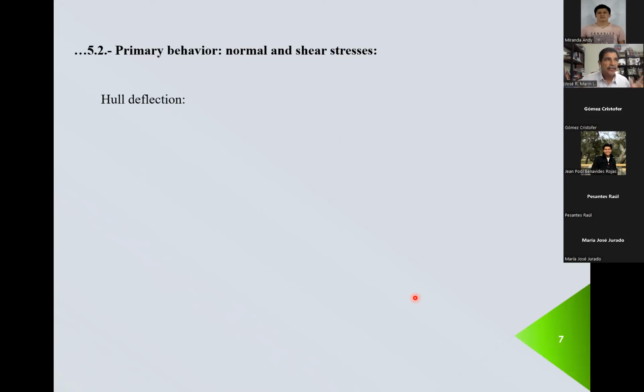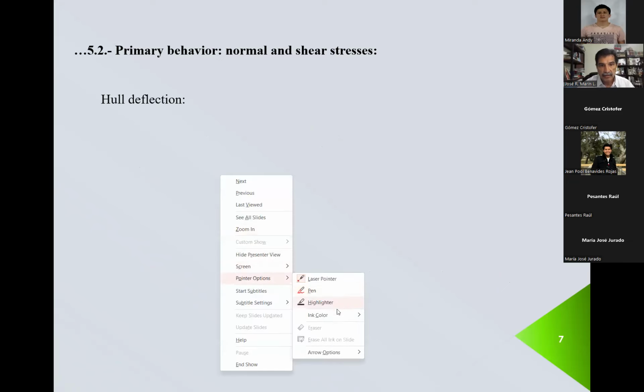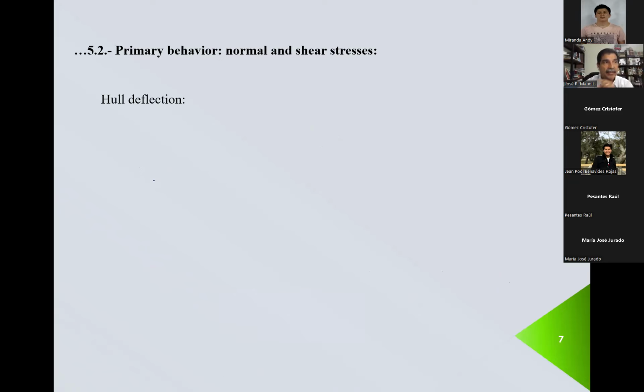Now, let's suppose that somebody is interested in the hull deflection. The problem with this is that there are no geometric boundary conditions. You cannot establish one point along the length where you know that the deflection is a certain value. That means that we cannot evaluate the two constants of integration if we try to evaluate the hull deflection. I'm sorry, we have to live with that.